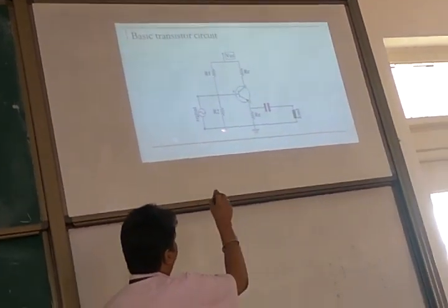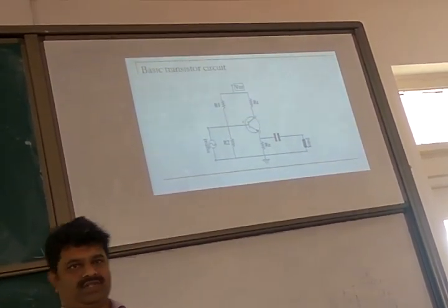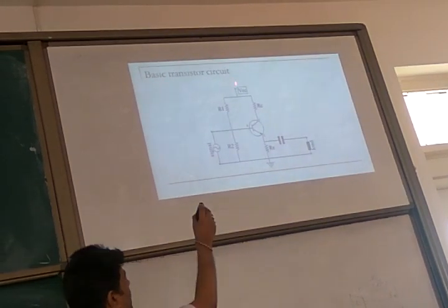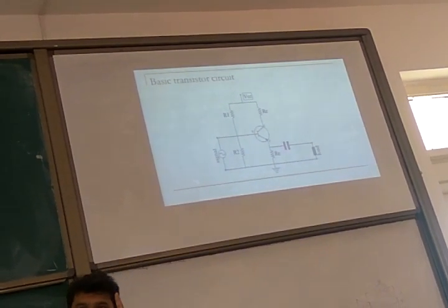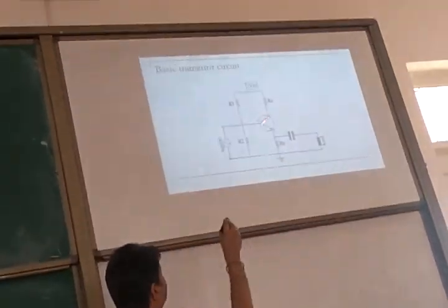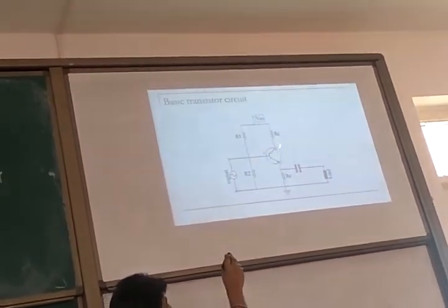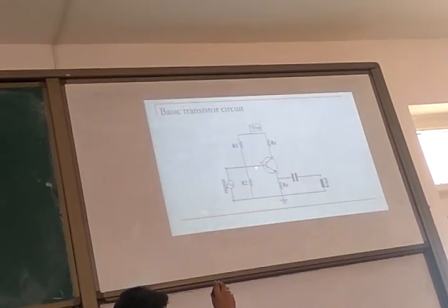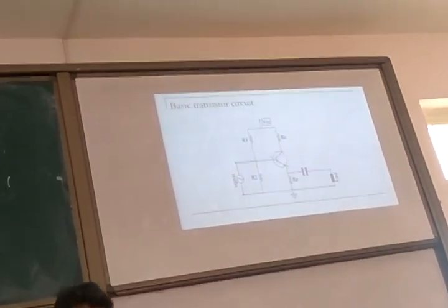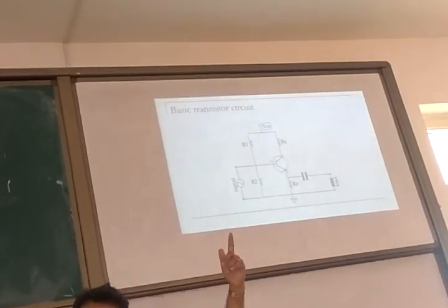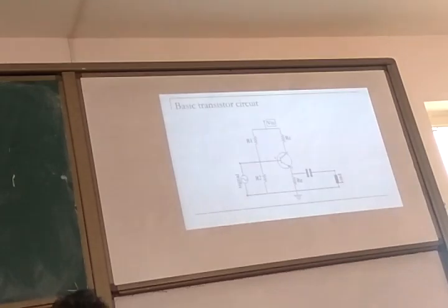So the bottom half of the PN junction is forward biased. I said I have connected a 12 volt battery. Here the instantaneous voltage is 1 volt. Now take the top half of the PN junction diagram. Collector is N-type material. Compared to 1 volt, 12 volt is more positive. Compared to 12 volt, 1 volt is negative.